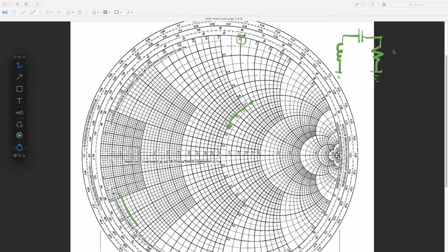resistance. Okay? This load resistance is 0.4. This impedance is around 0.49. Okay? And this susceptance is 1.2, so the impedance is 1 over 1.2. Okay? And so if you check the L match equations, you're going to get about these numbers, okay, of 0.82 for the impedance that's added here.